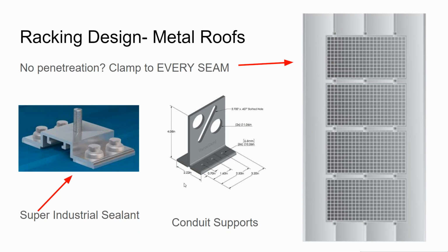And then the problem is, because these clips aren't cheap, maybe when you get into the interior of the roof, you can kind of take it easy with a scant number of clips. Maybe do every other like that. But particularly around the array perimeter, if you open up the standing seam racking guidelines, it'll say go into every single seam with your mounting clip.